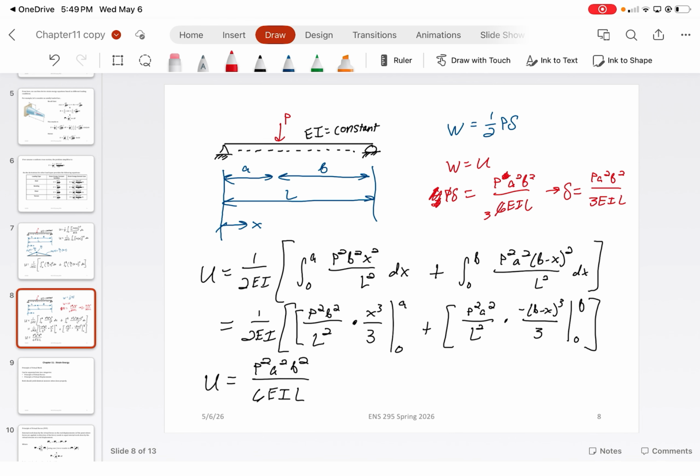All right? Now I invite all of you to look at figure 8 on this packet here, and just look at what the deflection would be at the point of the load. I have 2 of these packets here. No, I do not. Never mind. Looking at the deflection at the point of the load. Notice how it matches? That's just a standardized table of deflection equations. So ultimately we get that delta is equal to P A squared B squared over 3 EIL.